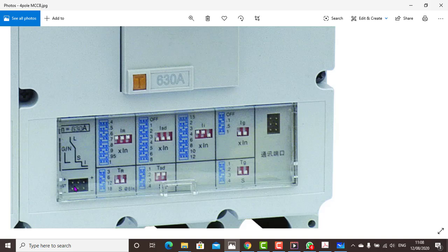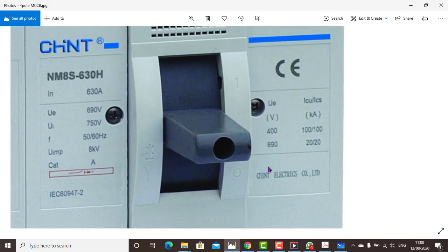So look at this pin you see here, it is for programming, or for when you want to collect data after tripping. So this is a test point. If you want to test whether the breaker is tripping well, press this system or test. If you press it in, it will trip. Okay, this is current rating. I hope you all understand this.